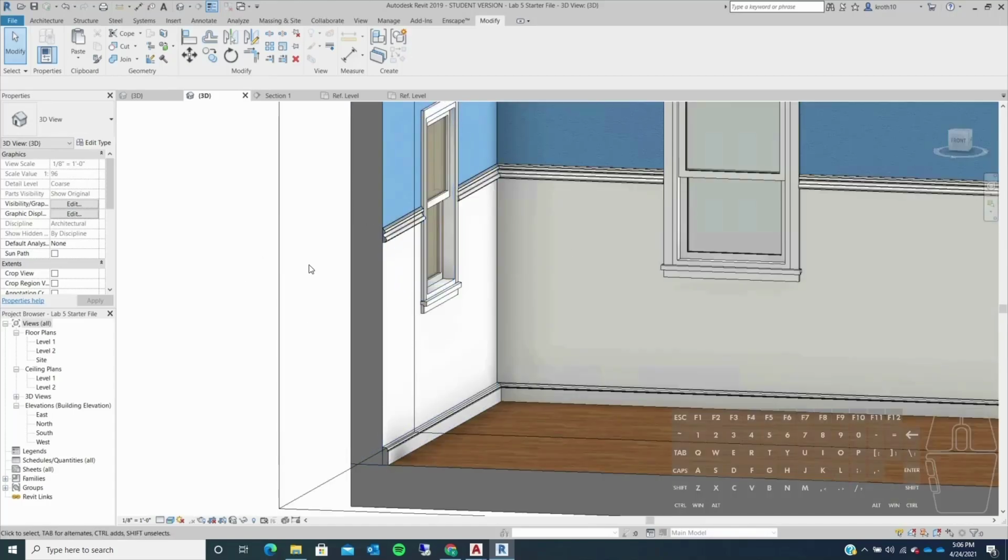But doing that in Revit is a little bit more complicated. And it really doesn't matter too much because usually if you'll be doing this, it's mainly for rendering purposes just to look good. So you can get away with just letting the bottom portion of the wall, by splitting the face of it, give the appearance that it is a panel that is actually sitting behind the rest of this molding.